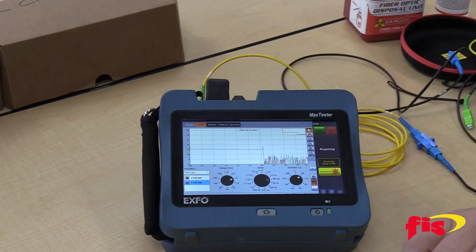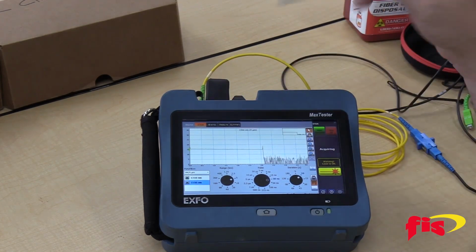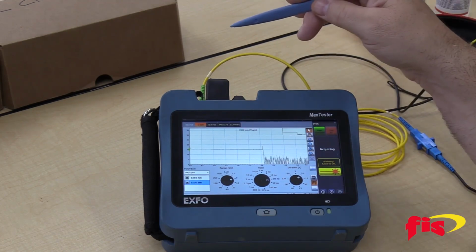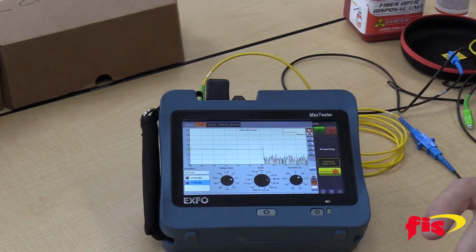Now, if I'm plugging into the launch cable instead, I only plug in once into my OTDR, and I plug hundreds of times into the launch cable. Yes, you'll wear that connector out, but you're talking a $20 repair compared to a $600 to $1,000 repair if we have to replace the connector in the OTDR. So that was that used car salesman thing where you can't afford not to have a launch cable, right? It saves wear and tear.